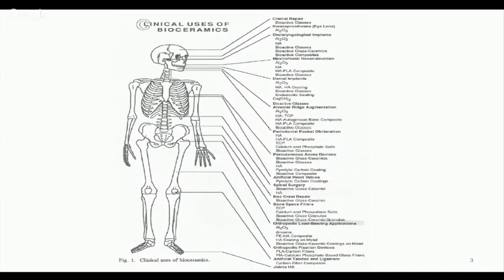But as we know, while you are chewing, the dentures actually flex and bend. So if you have alumina as a root, it will eventually break down. That is why we need to choose a root which has a certain amount of flexibility. So you can use titanium, right, or you can use some composite which can allow some kind of bending mode of operation.